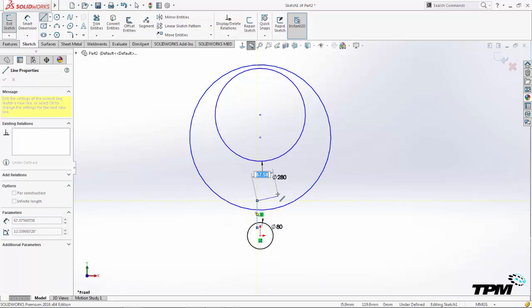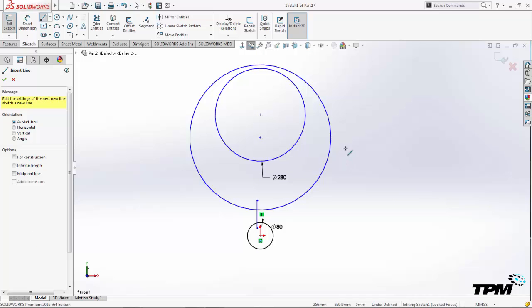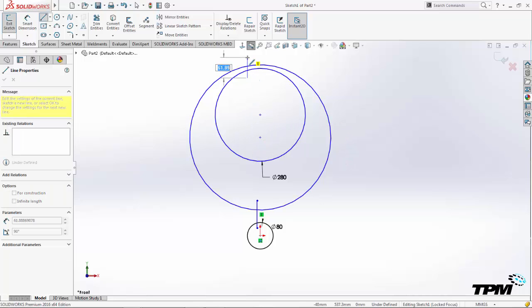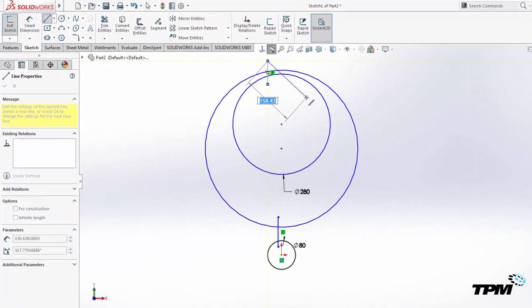Another trick is when you're creating lines and you're in a single contour here by doing the single click method. If you want to end that contour and stay in the line command, you can double click out in space. So I'm still in the line command and now I can sketch a separated segment somewhere else.